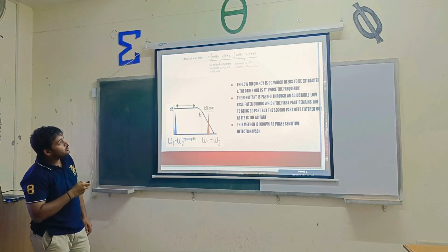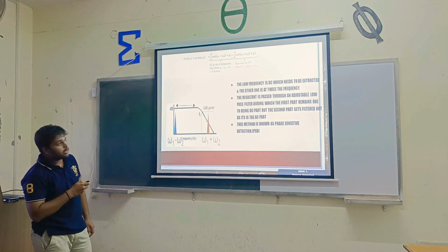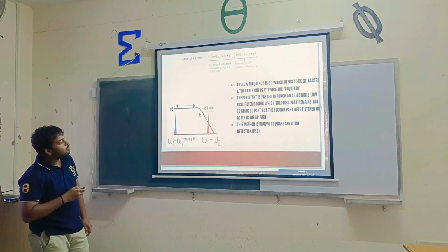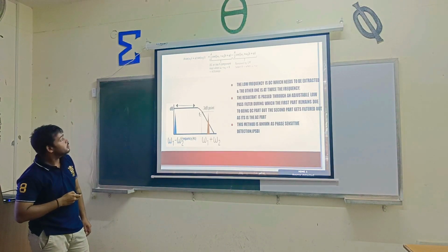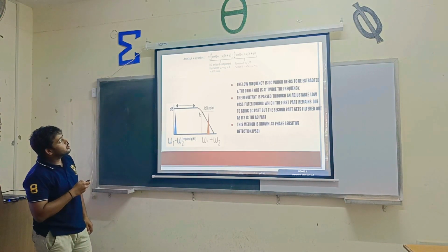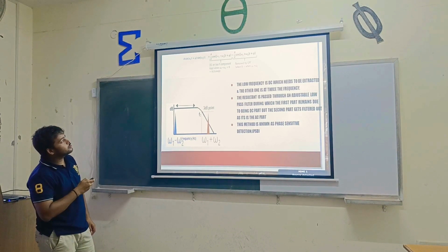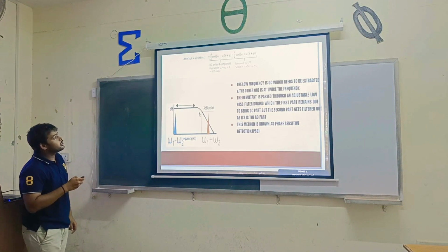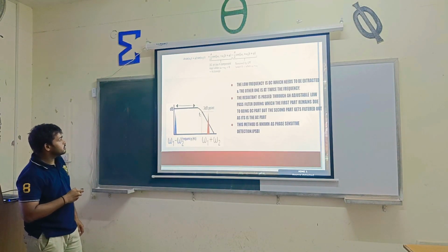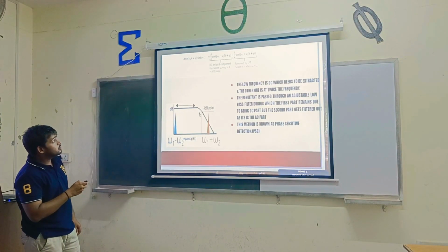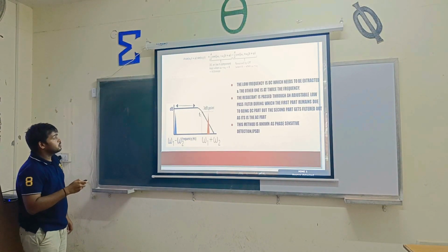This is the higher component, where the frequencies get added, and it is removed by the low pass filter, as you can see here. The other component is where the frequencies are subtracted, which results in a lower component. It is kept here, and it is generally a DC component, while the other is an AC component.